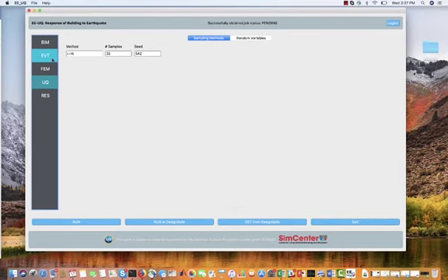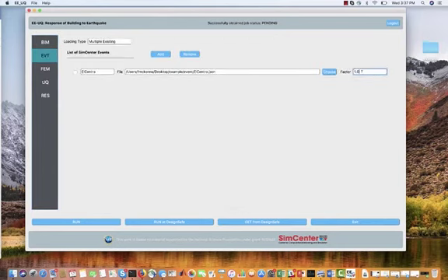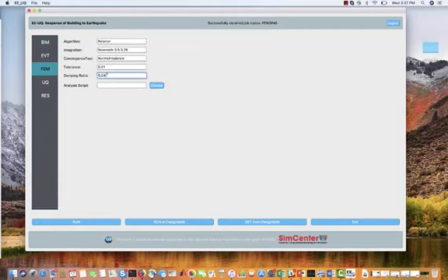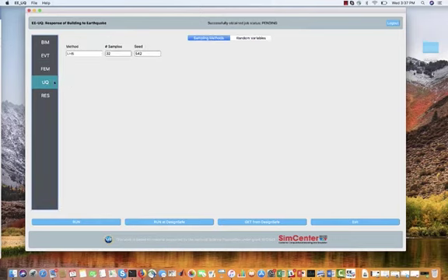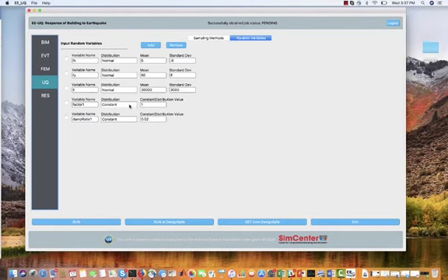Just to show you, we're not stuck with random variables in the model. We can do random variables with the event. For example, let's have a factor on the ground motion. Let's change the damping ratio to be a factor as well, say. And then we go to UQ, we go back to my random variables. I've got to set these values. So let's put a uniform distribution on the load factor. And the damping, why not the damping ratio as well?